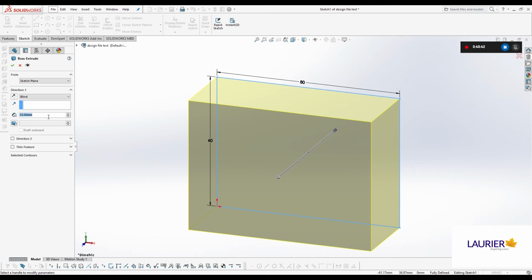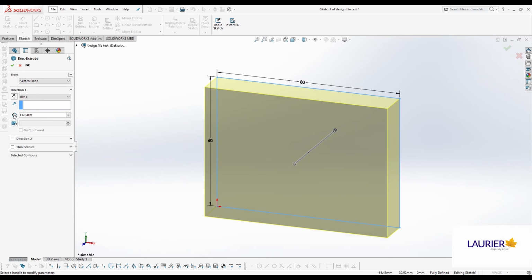And we're going to make this thing out of 3 layers of our 4.7 millimeter plywood. And I'm pretty sure that 4.7 times 3 is 14.1, but I'm not 100% sure. So I'm just going to type in 4.7 times 3. And then I'll click anywhere, and that gives me 14.1, and it adjusts the part to that size. And my nice yellow 3D preview here, the kind of translucent yellow 3D preview, looks good, and I'm going to say yes.